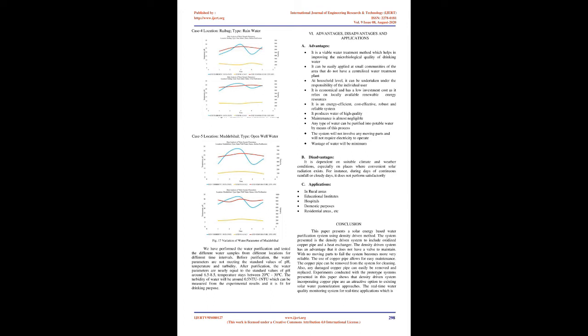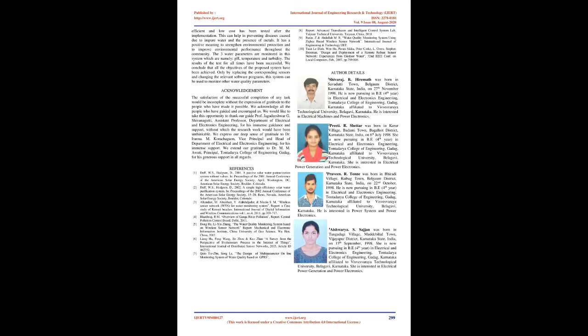Fig. 12 software systems. The pure water can be monitored by using a GSM-based water quality monitoring system using Arduino Uno. We are using 3 sensors, namely pH, temperature, and turbidity sensors. All the sensors are immersed in the container containing the purified water, which is subjected to its quality test, and these sensors are connected to the ADC. The ADC is connected to the Arduino Uno. In this, the coding is dumped. The output of the Arduino Uno is given to 2 systems, namely GSM and LCD.